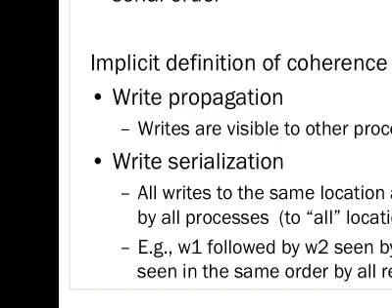We'll see in the next example that when we write values to this shared memory, because of the distance of the processors, how these updates are populated may vary. It may happen that these processors will see different values at different times in different order, and that's not what we want. That's not the coherence we want to achieve.